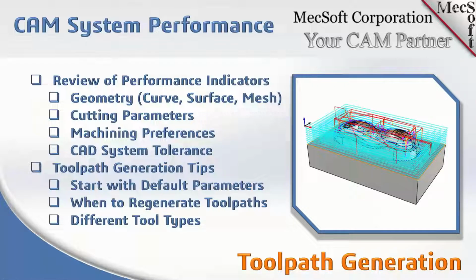Typically, your CAD system tolerance is set at 1,000th. At times, you may increase or decrease that. Probably wouldn't want to decrease it a lot less than that. But regardless of what it is, it contributes to the amount of information that's cooked into that surface. So it will add some time. It won't be very noticeable, but it does add some time.